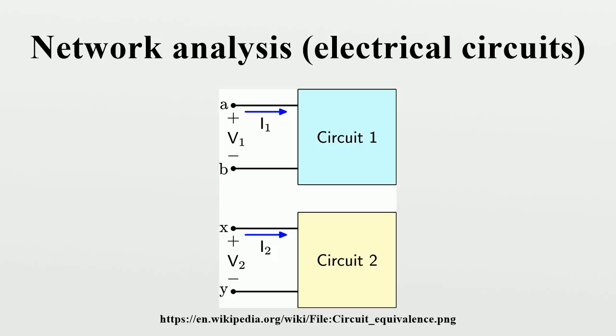In network analysis, rather than use the differential equations directly, it is usual practice to carry out a Laplace transform on them first and then express the result in terms of the Laplace parameter S, which in general is complex. This is described as working in the S-domain.